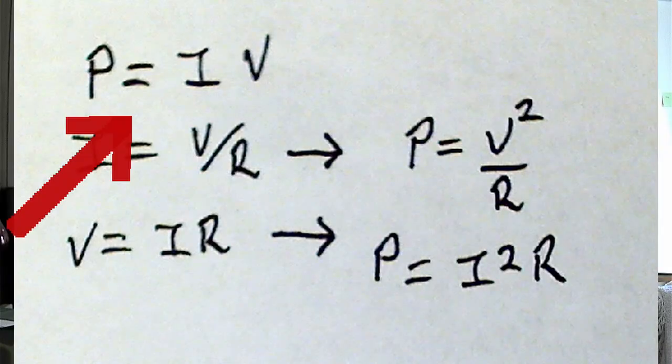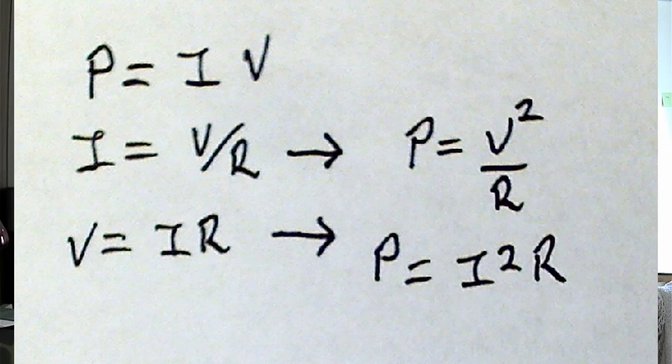Before I go, of course, I need to discuss how do you actually calculate the power dissipation in your resistor? Well, it's not that hard. What you need is the equation for power, and then you plug in Ohm's law, and you can either get P equals V squared divided by R, or P equals I squared R. Those are equivalent. It just depends how you want to describe the operating point of your resistor.